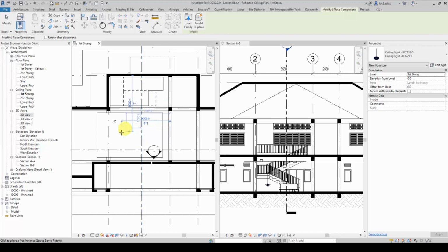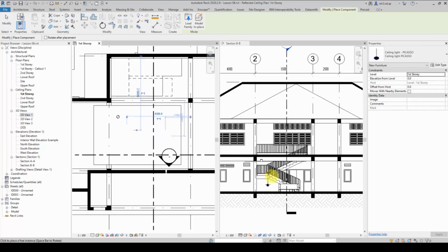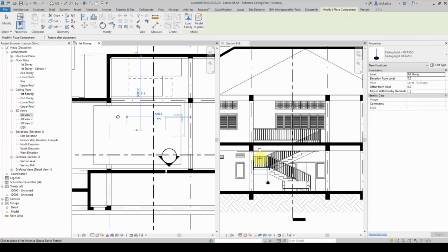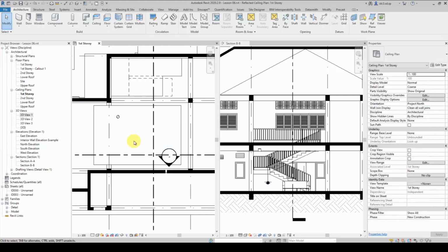Let's say down here, and I'm going to see what is the highest point here to my ceiling. What's the distance? The distance is about 1030.5 or something like that. Okay, so I'm going to just click on this element here and change it to 1030 point, let's say 5, like that. And there you go. I can now attach this one quite nicely to the ceiling already, like that.